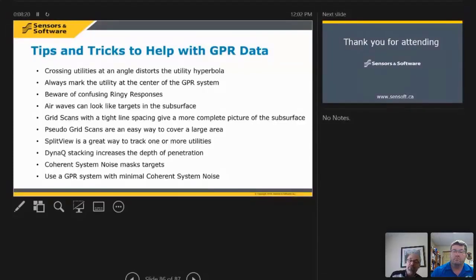What normally happens though, people will start looking at the GPR screen because they're interested in seeing stuff. And you have to say, no, don't look at the screen. Look at the screen when you're done the line. And when you're done, walk straight. Your only job is to walk straight. And when you hit the far end, then look back at the data and see what you've found.